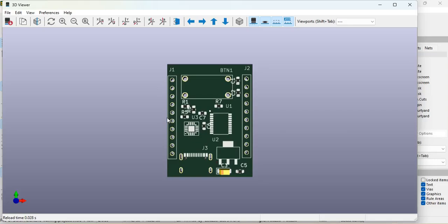One important aspect of PCB layout design is the aesthetic. The aesthetic view is very important. For example, someone might want to have this particular USB Type-C connector at the center of the PCB. That is a very important aspect for their design. But if you are doing a design and you don't need that aesthetic view, you can place it here.